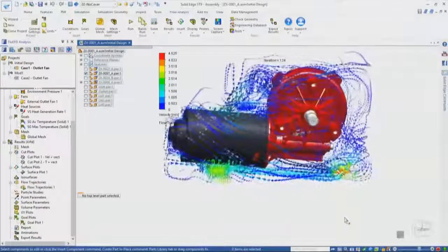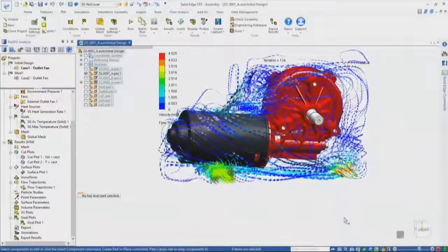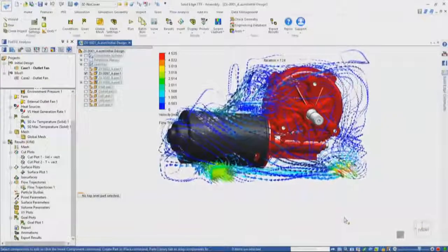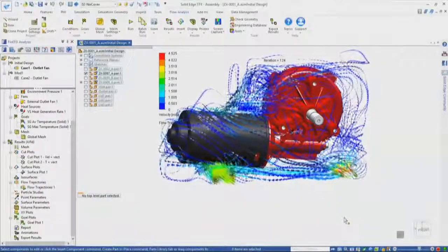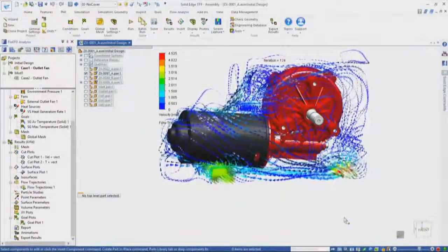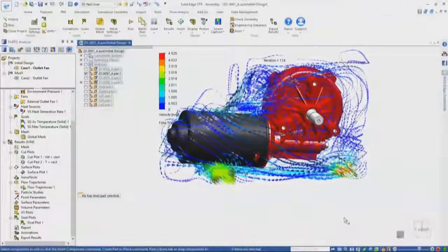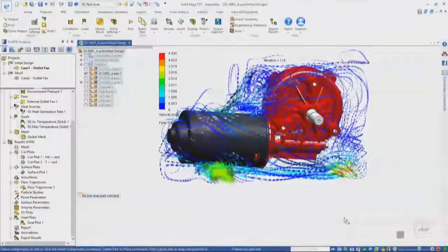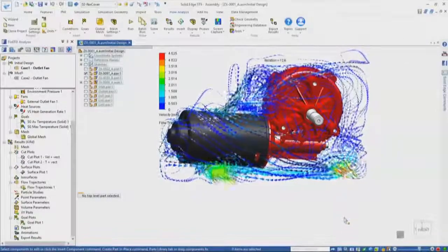And so if we look at our problem, just to understand this flow field, the flow comes in from that inlet, and it has enough momentum that it goes to that back wall, impinges, and spreads out throughout the compartment there, which is good, although there's a decent portion that looks like it stays low and then heads out and leaves through our fan. So that whole amount of the flow really probably isn't doing much of a job with respect to cooling.